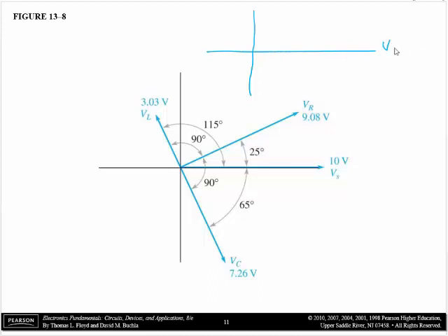I had VR here, I have R here, I have I here, and then I have Z calculated this way, and this is at 25 degrees. So that's exactly the same as this VR, I. But what's weird is that R doesn't really go in this direction, but there's that 25 degrees. So there's the same 25 degrees. So it's like the author's phasor diagram is rotated 25 degrees from how I would normally draw the phasor diagram.